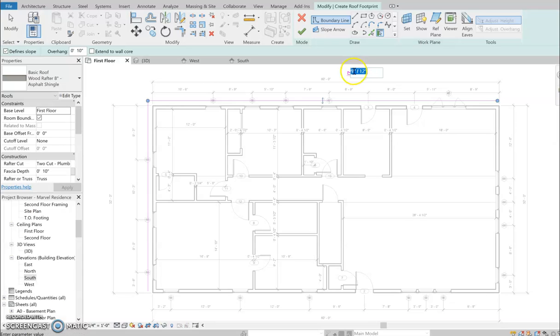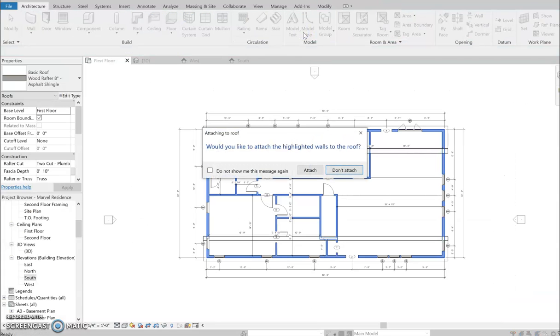I told you I would like to have an 8-inch pitch, so you can change that right here as we're designing our roof. I just hit the enter button after that. Going back to clicking off define slope for gable end, making sure my overhang's on the outside, and going back to define slope and making sure my overhang's on the outside. Again, this is a nice simple roof. If we have time, maybe we can add a little porch roof to this so we can play around with the secondary roof coming into here, but let's just go ahead and click on the green arrow.